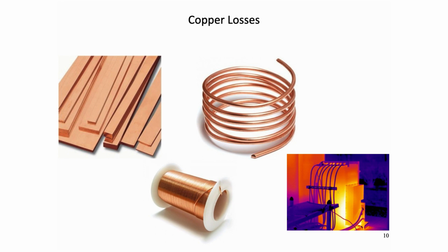Not only that, when a load is connected to the transformer secondary windings, large electrical currents flow in both the primary and the secondary windings. Electrical energy and power, or I²R losses, occur in the form of heat. Generally, copper losses vary with the load current, being almost zero at no load and at a maximum at full load when current flows at a maximum.